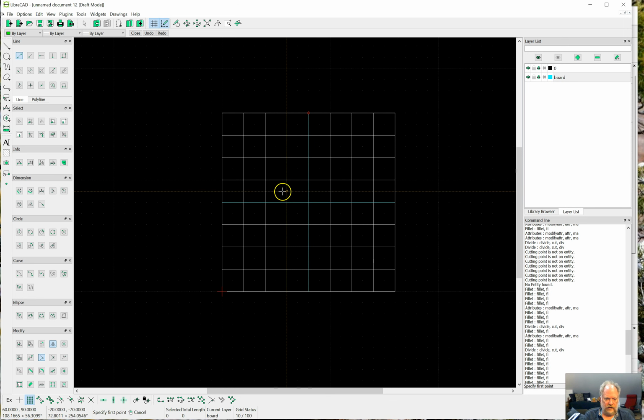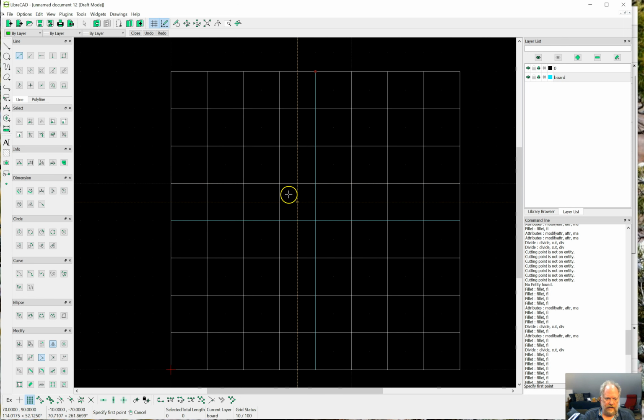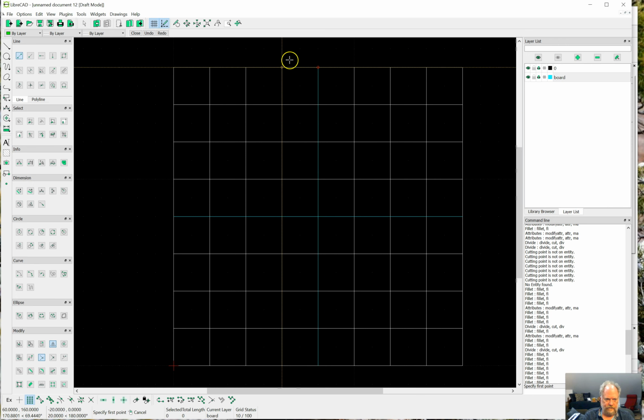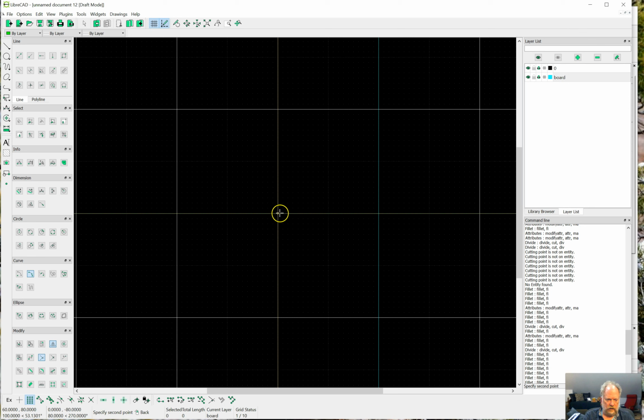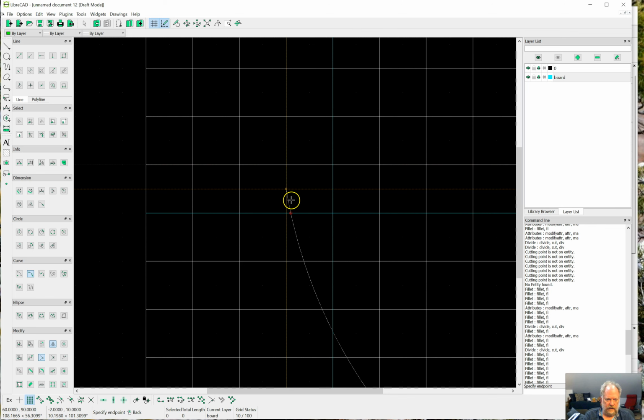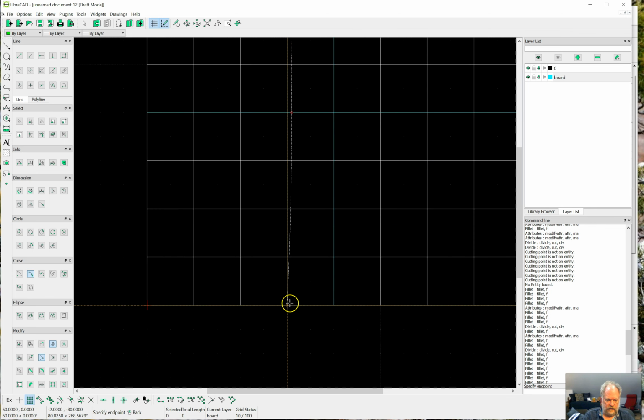Now I'm going to make my first curve. This is a little harder to do on the smaller screen. Oops, I did not want to do that. I'm going to cancel that. I want to do a curve, so I'm going to choose this 3-point curve, and I'm going to click here, and then I'm going to zoom in, and I think I'm going to go in 2 units. Let's see, 1, 2, and then I go down here and connect it to the bottom, like so.